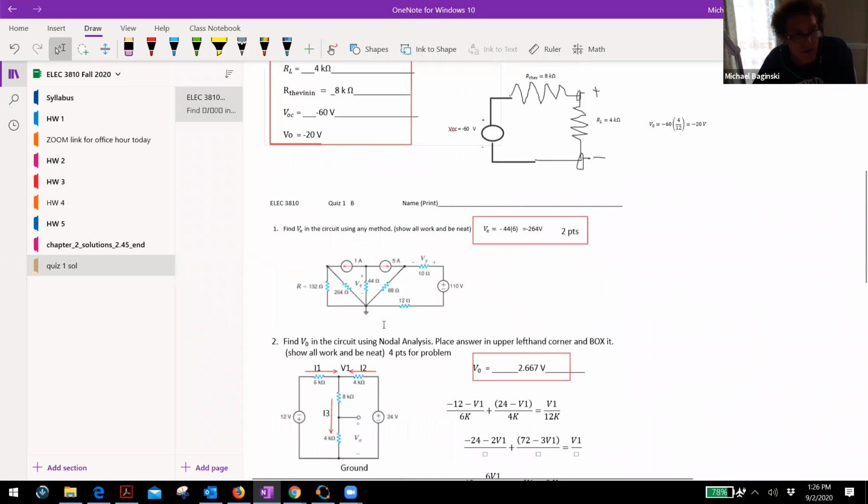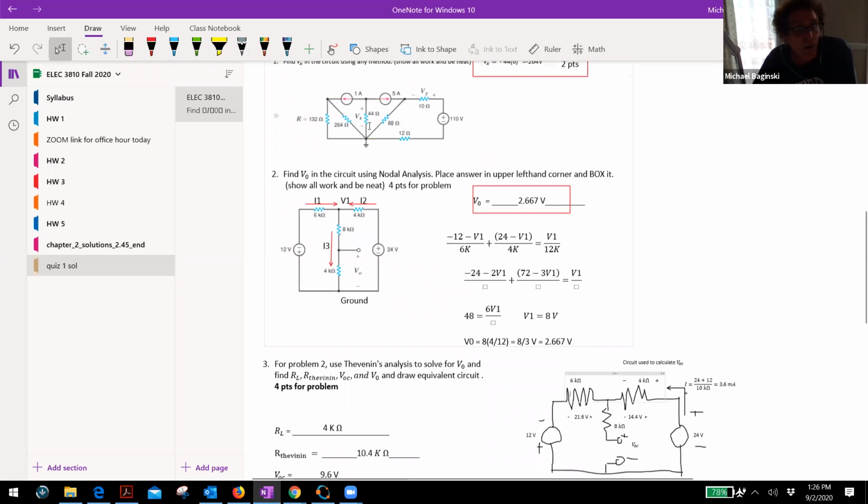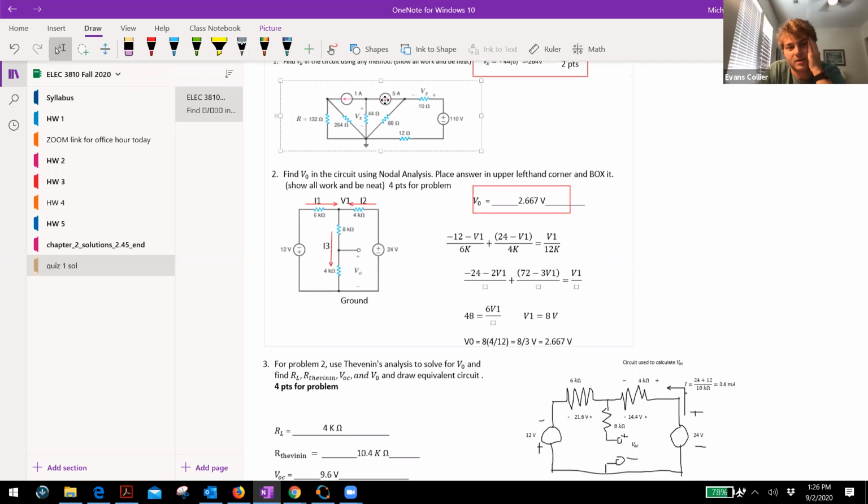The bottom part here is labeled positive and the top part negative, because current enters the positive, leaves the negative, correct? With the bottom labeled negative, the top's labeled positive. Because current enters the positive terminal as you sense voltage and leaves the negative, right? Yes. That's it. So it's negative because the signs are negative, positive. This is like putting a meter on there: I put the positive side of the meter on the top, the negative on the bottom. What would you read? You would read a negative voltage.